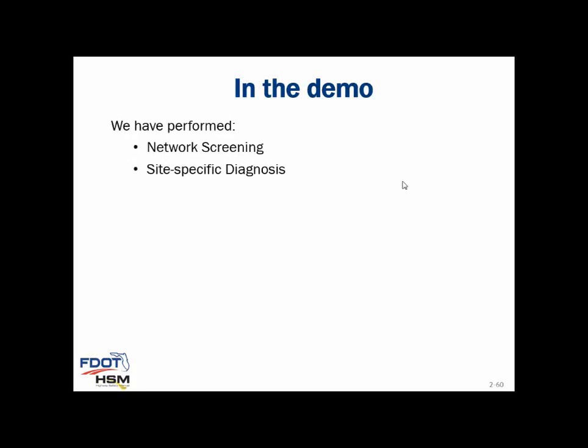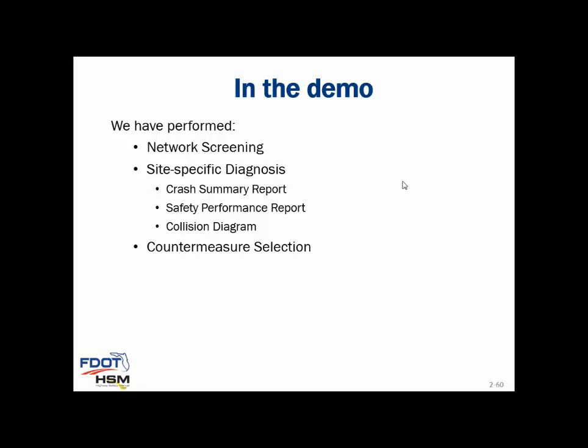We conducted site-specific analysis. We have generated crash summary report, the safety performance report, and the collision diagrams for one intersection. We have selected countermeasures, we've conducted economic appraisal, and we've also evaluated countermeasures.